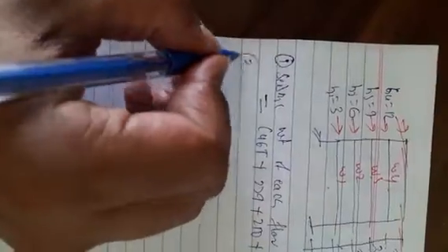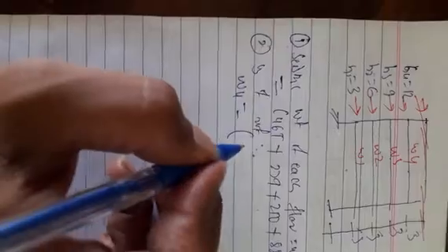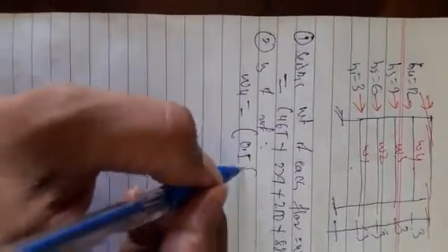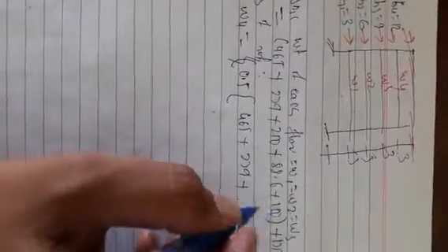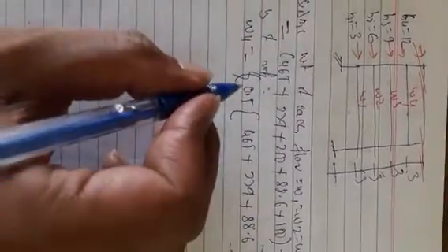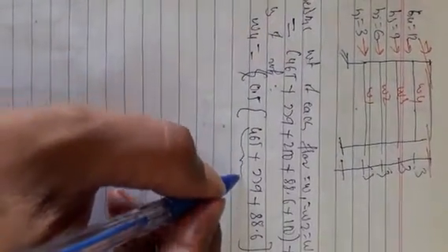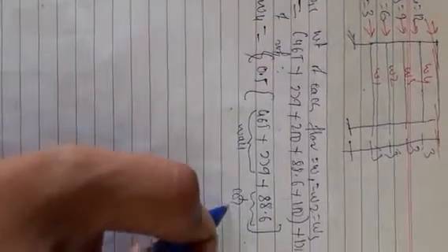Next, seismic weight of roof, W4 is equal to, so what the code says is you have to consider 50% of wall loads, 465 plus 279 plus 50% of column, that is 88.6, 50% 0.5. So these are for wall, this is for column.